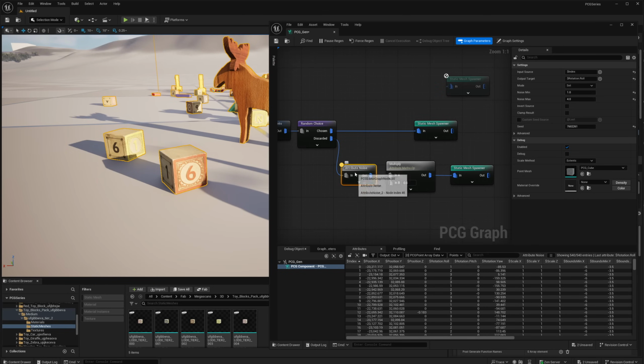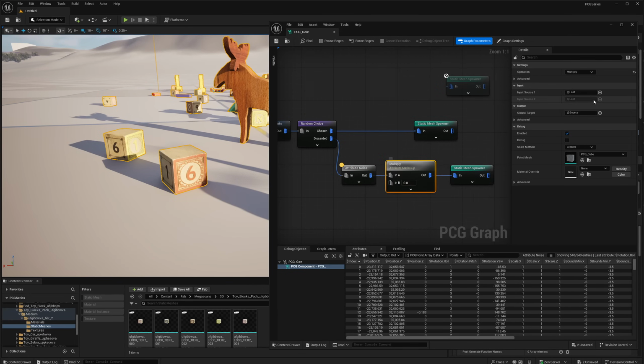And if you mark your previous node and look here at the top right of the attributes panel, it will say last attribute rotation row. And if I select here my multiply, this last is referring to this rotation row. And it's the same as putting here $ rotation.row.